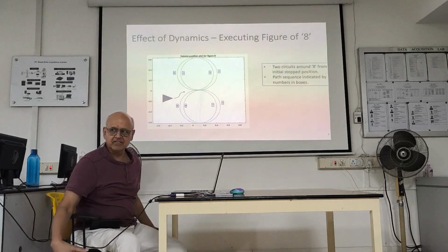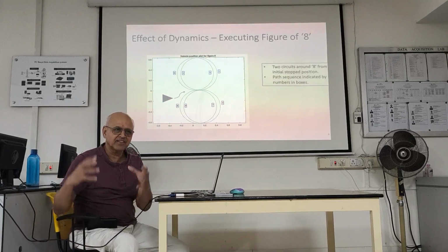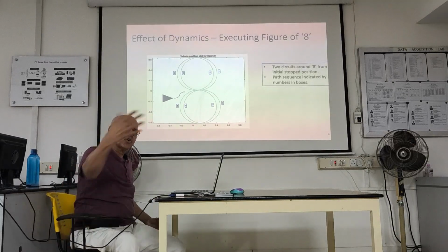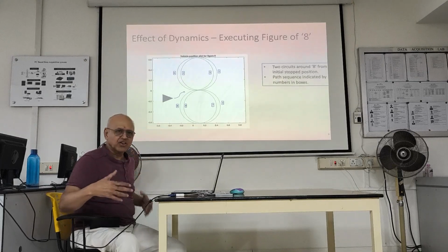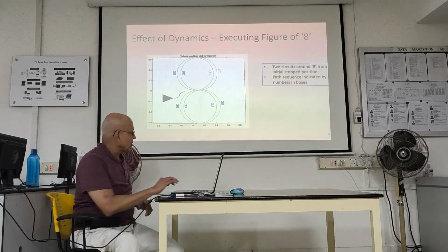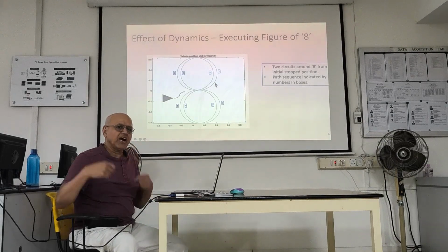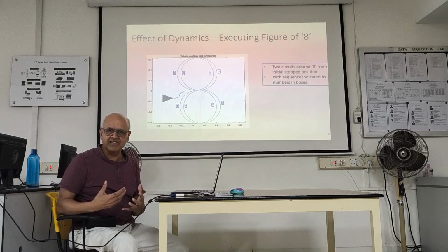And I'm assuming they are the same motors. Like, not the same motors, but identical motors. You bought it from the same manufacturer. You bought 2 of them, right? So you start at 0, 0, and one has to go further than the other. The right has to go further than the other, right? So it's going to take a longer time, right? So kinematic model will be valid at each instant, but you haven't immediately got to the target velocity. You have to use the acceleration to get there.